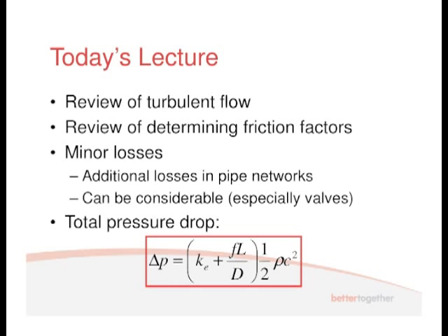We have a globe valve in your list that has a K value of 10. If that valve was, say, half closed, that pressure drop suddenly shoots up by a factor of 10. The K value would be 100. They can be quite considerable valve pressure drops, and for good reason. We like them, we use them all over the place to reduce the pressure in the system.